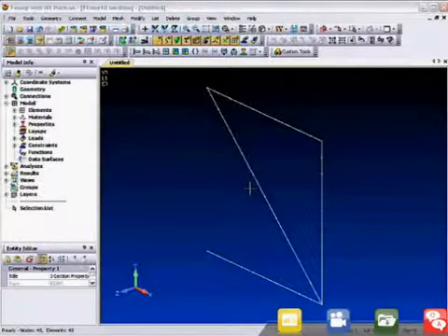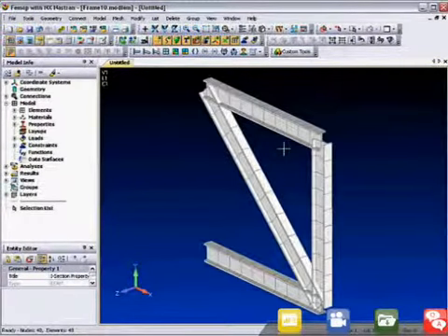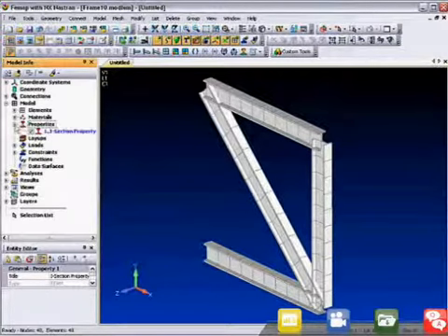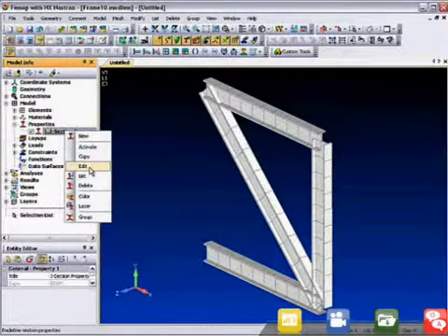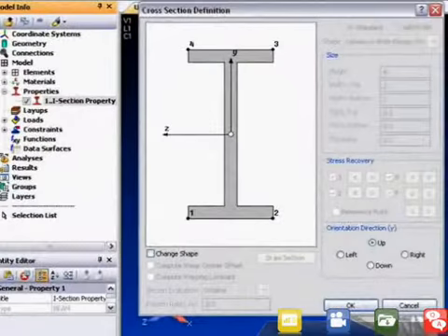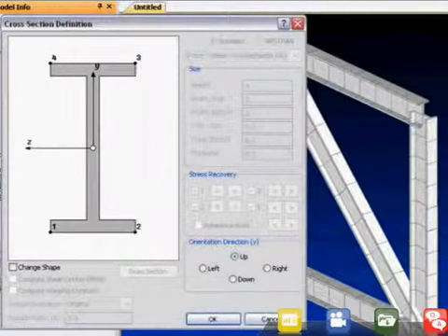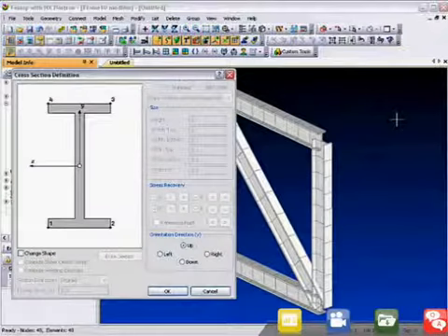Beam elements are a very powerful way of simplifying the modeling of long and slender components in the design. However, as one-dimensional elements, beam visualization can be difficult. For post-processing, many solvers require you to define the points of interest on the cross-section where data will be recovered ahead of the analysis. The trouble is, you don't necessarily know where to expect the highest stresses, and shear distribution details cannot be readily determined or visualized with most programs.